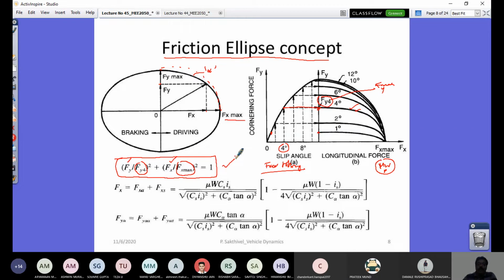But it doesn't show explicit appearance of your skid and slip angle. That's where your Fx and Fy come into the picture. When you do straight motion and you have a side force, that is accounted here. You see C alpha and alpha here. When you do cornering, you will have a skid, which is accounted here.